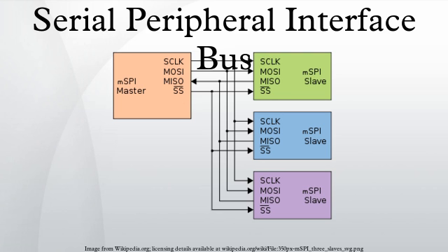Valid SPI communications. Some slave devices are designed to ignore any SPI communications in which the number of clock pulses is greater than specified. Others do not care, ignoring extra inputs and continuing to shift the same output bit. It is common for different devices to use SPI communications with different lengths, as, for example, when SPI is used to access the scan chain of a digital IC by issuing a command word of one size and then getting a response of a different size.